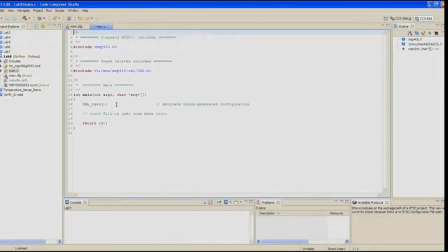In step 10, let's modify main a little bit. Remove the arguments in the main declaration. We're not going to use them. And then remove the return at the bottom. We're not going to return from main. In order to save some space in the workbook, we removed some of the comments. You don't have to remove those if you don't want to. So the only thing that you should have inside main at this point is CSL init.